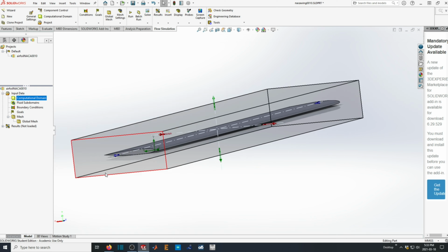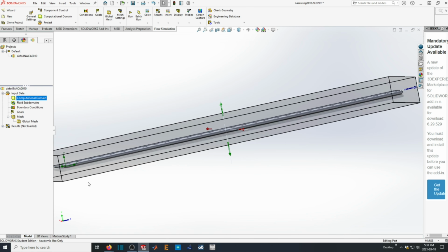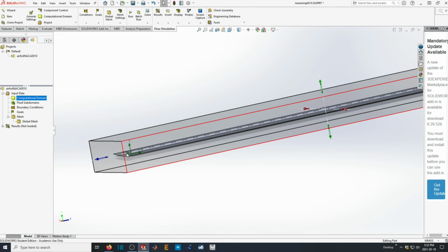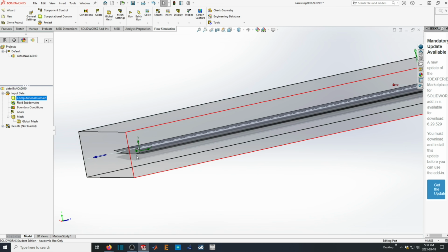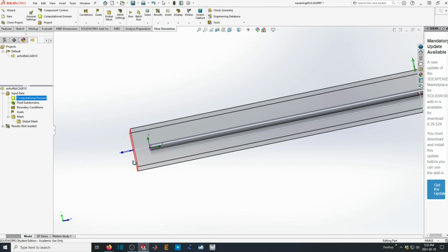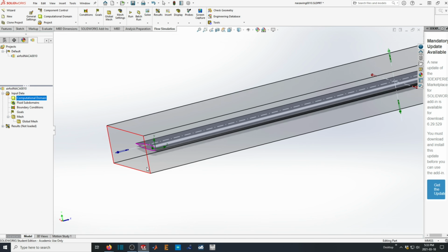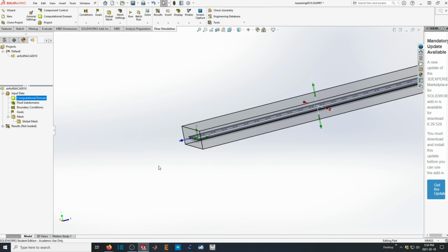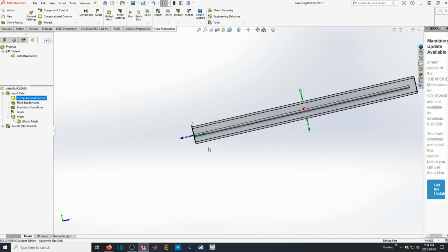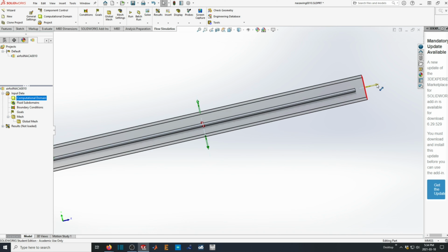The other thing that you notice is that the ends are within the model, which means that there's a gap between the computational space and the end of the wings. And I want this as best as possible to be a two-dimensional representation. So I'm just going to move that to 0, which is where my hydrofoil starts, and I'm going to move this to 1 meter.